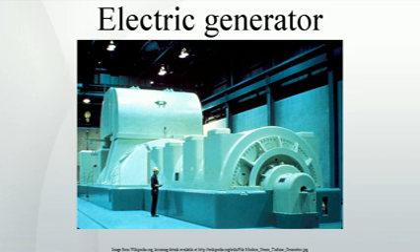Terminology. The two main parts of a generator or motor can be described in either mechanical or electrical terms. Mechanical. Rotor, the rotating part of an electrical machine. Stator, the stationary part of an electrical machine. Electrical. Armature, the power-producing component of an electrical machine. In a generator, alternator, or dynamo, the armature windings generate the electric current. The armature can be on either the rotor or the stator.